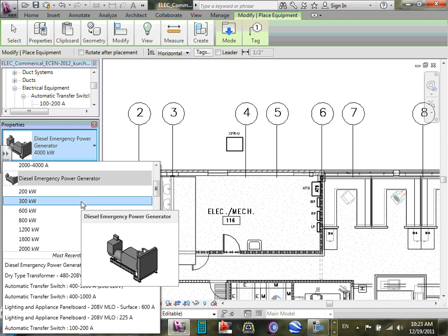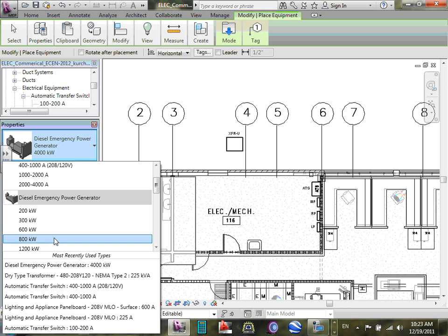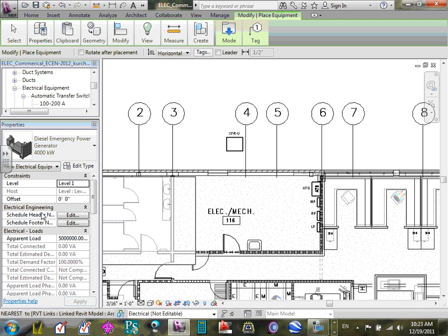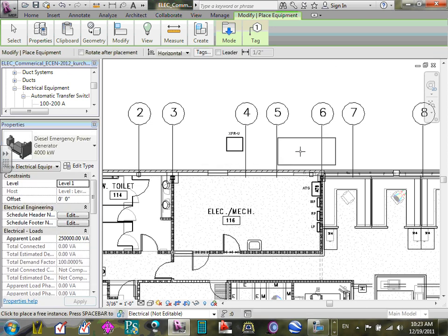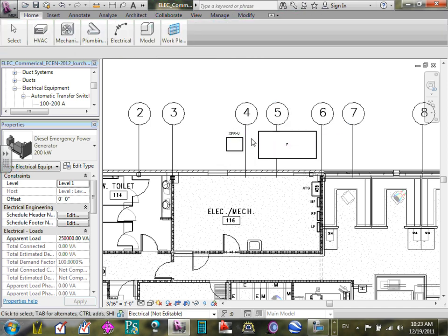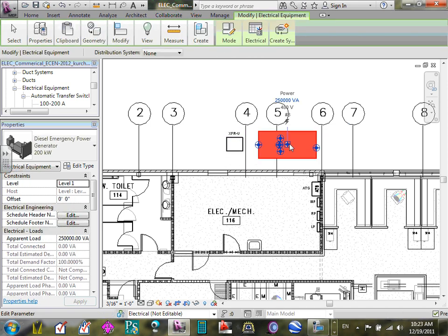Later on, guys, I'm going to give you a software that you can size the gen with, and if you come up with a different size, guess what? We're going to go change the size here. So I have 144 kW. What's the next standard? Do I have 144? Do they even mess with 144? My next standard is what? 200 kW. Okay, here's your generator, Ashley, right in here. Everybody downloaded 200 kW.